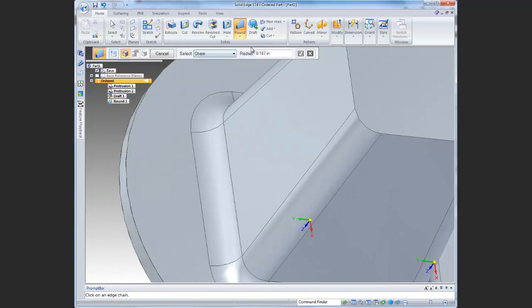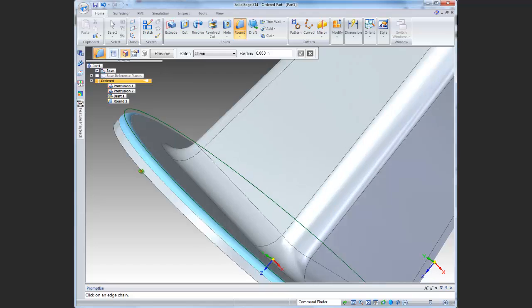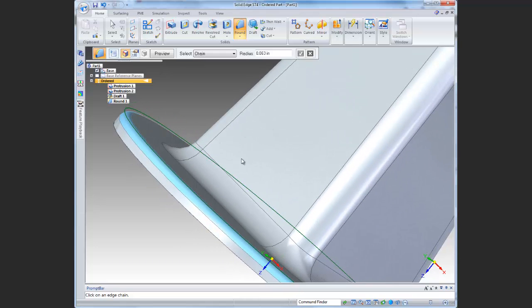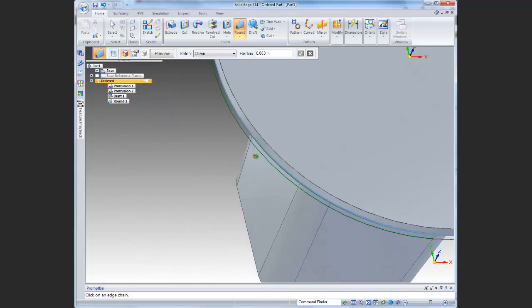So I'm going to, it selected radius for me, which is great. This one could be about any radius. There's no requirements. I'm going to put on a 1/16 radius just because I picked it, right? Nothing special about that. So I'm going to put it on right there, and I'm going to check that. So those are the important things to do for looks, and it's also going to help us because it's now the smooth thing. A chain will go over a smooth radius. Cool, so almost there, making progress.